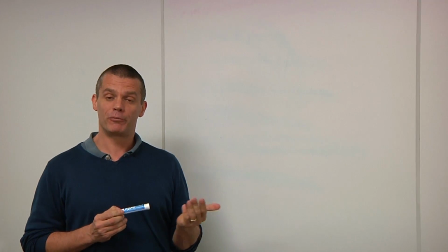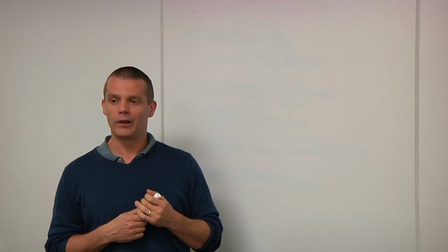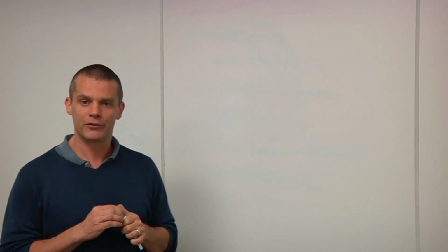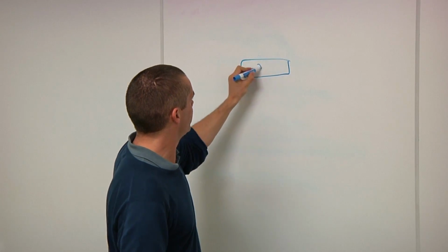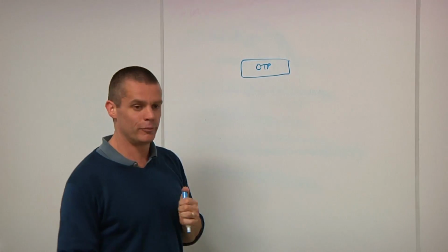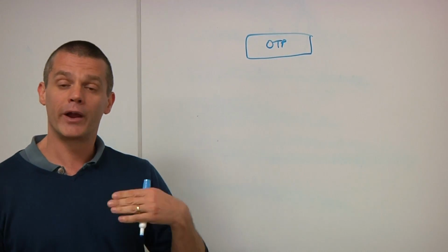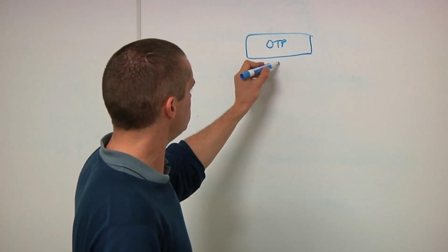Yeah. If that's the set of properties that we aim for with an integrated root of trust, what does it look like in implementation? And actually, from a block diagram perspective, it's quite simple. So I'll try and show you that. So firstly, you have a set of OTP. Typically, we think of it as being private or protected one-time programmable memory that we're going to use to store some of the foundational keys.